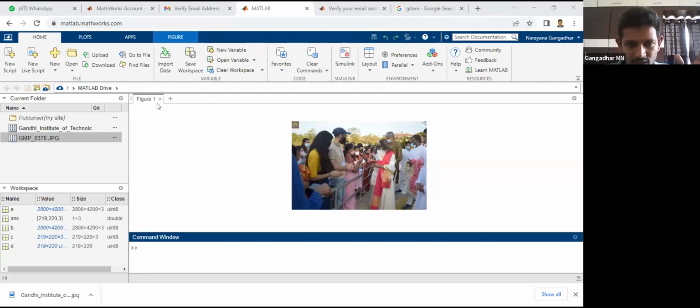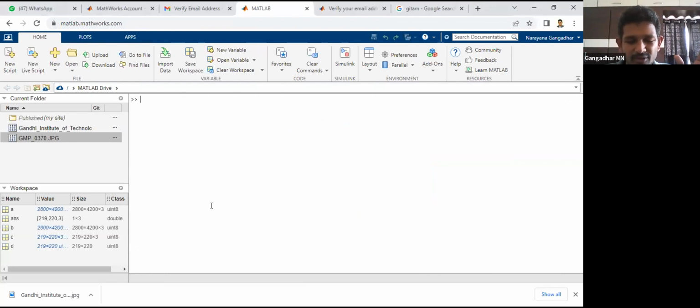So coming to the signal generation, this is how it works. If you're, let's say, a second year student, and you want to generate a sine wave, first we define one matrix for the time axis, 0 to, with an increment of 0.01 seconds, to 1 second duration.